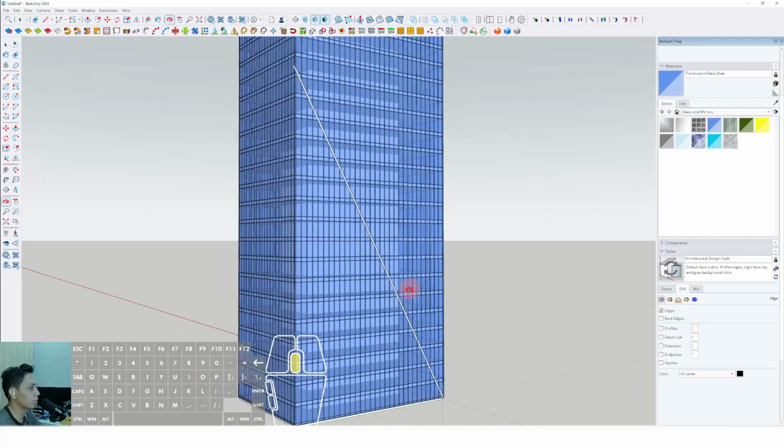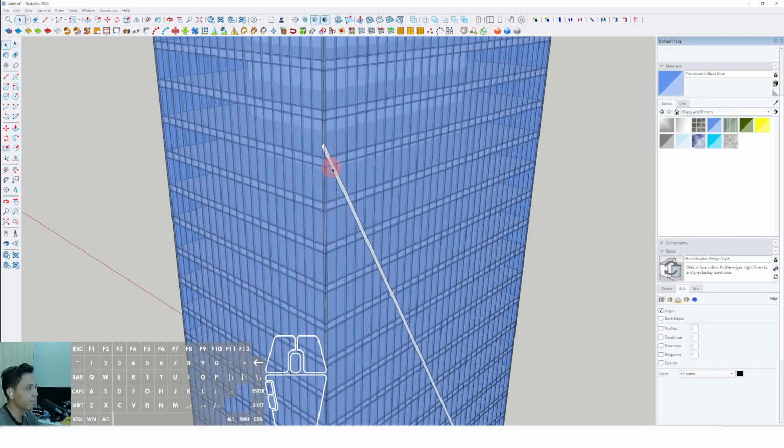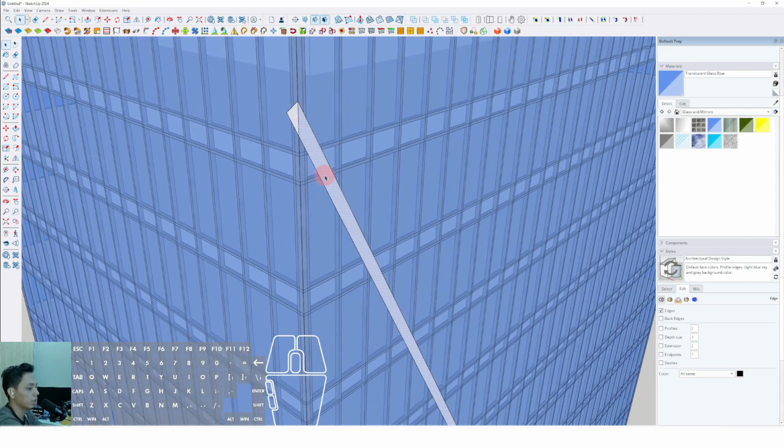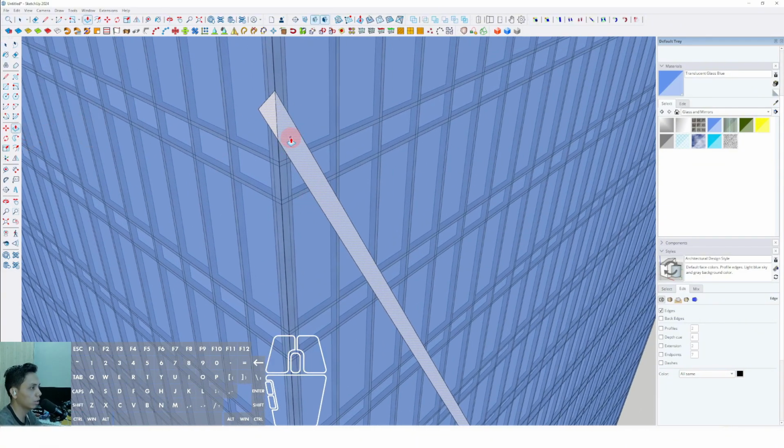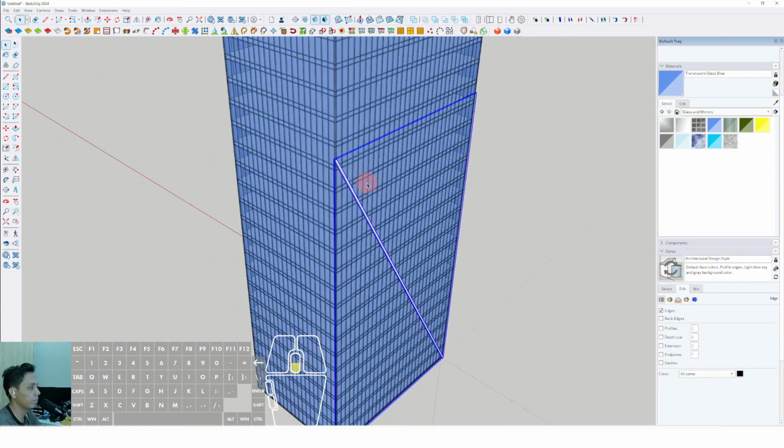Okay, this is about 500, and you have to click this plane and select a push tool. You can select a push to the another position around 300 approximately. Double click or right click and make group.